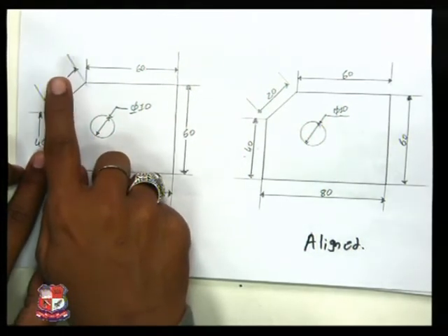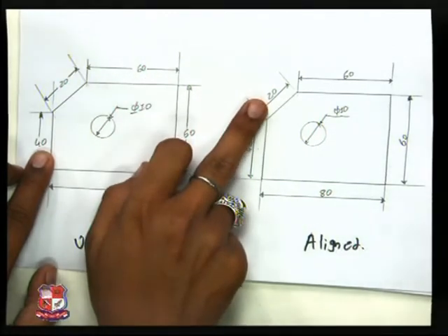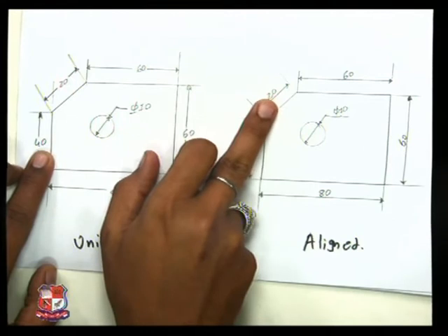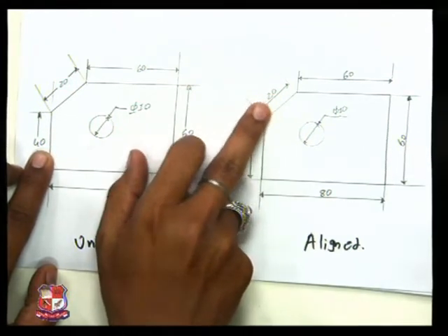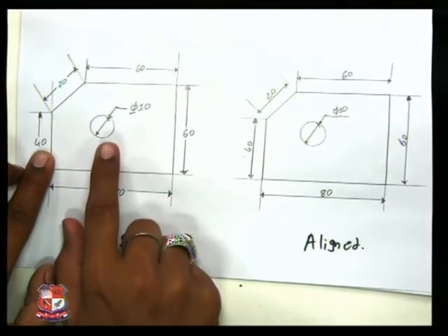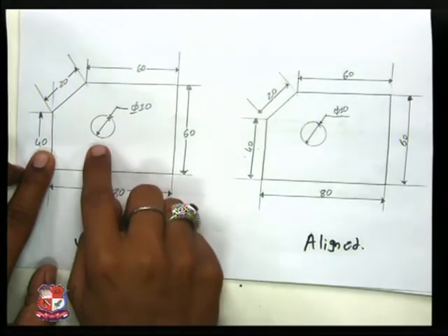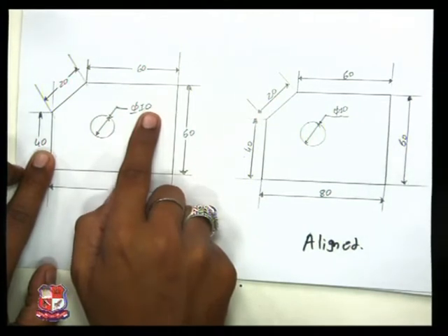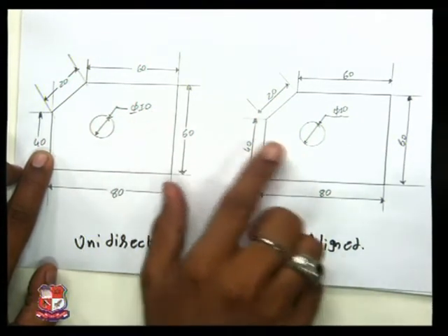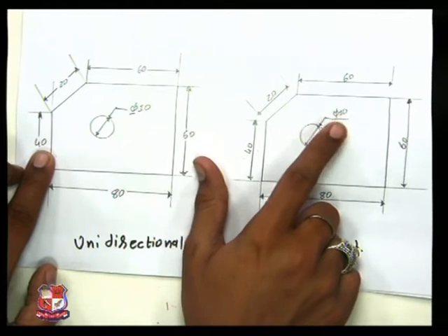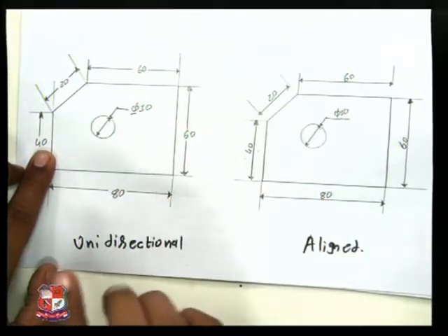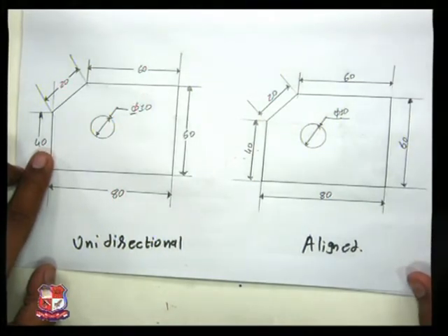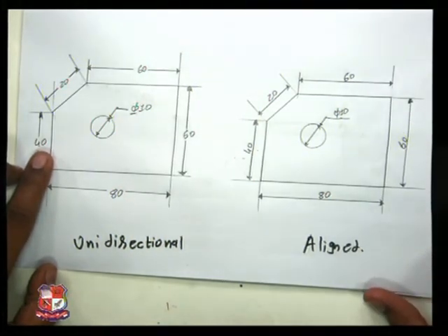Dimension can be visible from the front side itself, whereas over here dimension is above dimension line but parallel to the line. For the circle, closed filled arrow on both the sides, dimension written beside the extension line, dimension written above the extension line. So this is the clear visible difference between the two dimensioning systems.